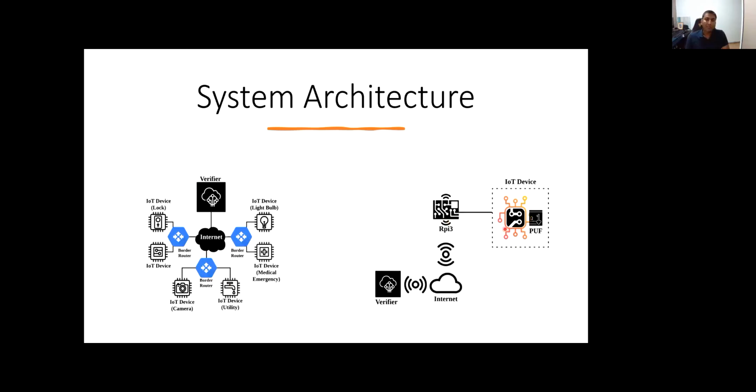So normally, if this would be an Arduino sensor, okay, then the gateway can be a Raspberry Pi, which is also considered an IoT device, but it's more powerful in the typical sense. So normally when we carry out experiments, we would use a Raspberry Pi as a gateway instead of the IoT device itself. And then the Raspberry Pi can be connected through Wi-Fi to the server or cloud. Okay, so this is how normally you would start off to create an IoT device, and the Arduino over here would be programmed to do different things depending on the sensor or what application you want to do.